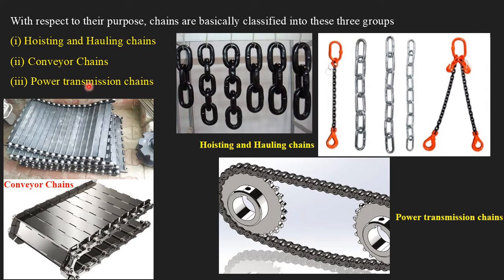So that is the application of conveyor chain, and one more is the power transmission chain, on which our focus will be. Our numerical solution will be mainly based on the power transmission chain, which you are very much familiar with, and which is mainly used for transmitting power from one shaft to another shaft. They are usually used when the distance between the centers of both shafts is medium or short. If they are too long, then the transmission efficiency in these types of chain drives will be lesser.